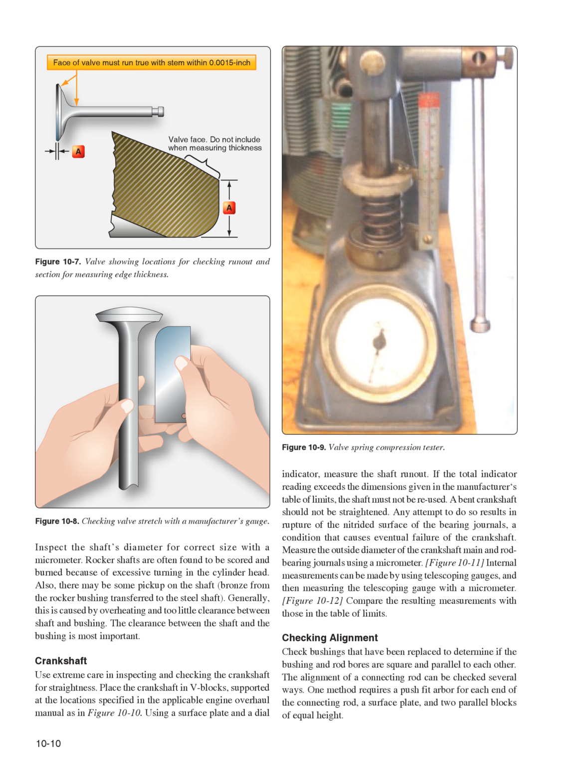Generally, this is caused by overheating and too little clearance between shaft and bushing. The clearance between the shaft and the bushing is most important. Crankshaft. Use extreme care in inspecting and checking the crankshaft for straightness.